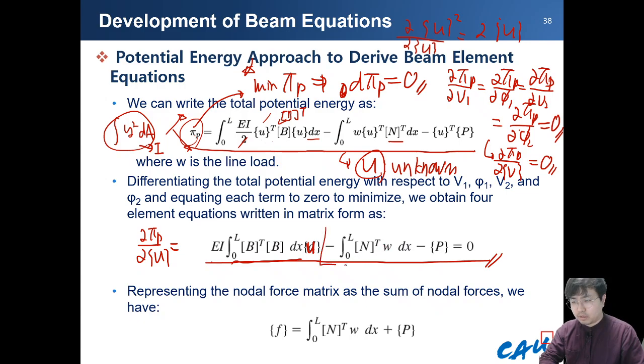However, in these two terms we can indicate that the distributed forces and the external load forces equal the force, and this part becomes the displacement U, and the remaining thing is the global stiffness equation.